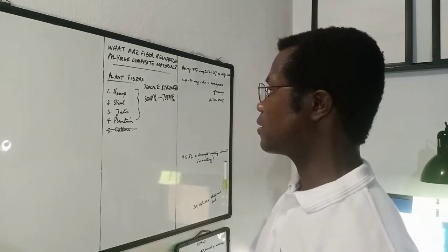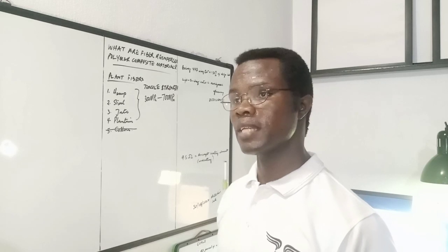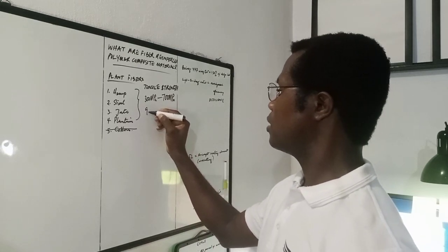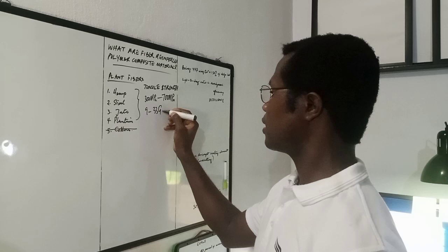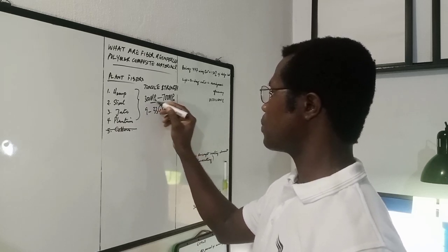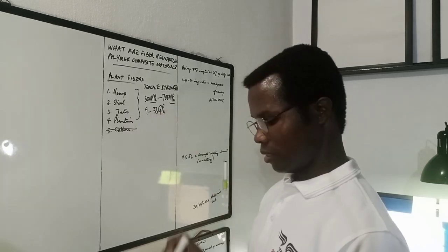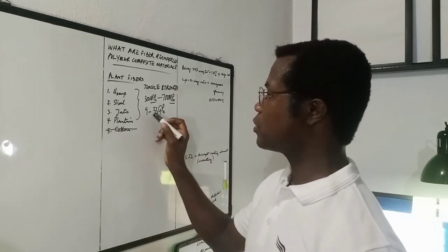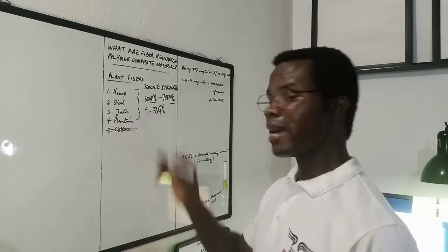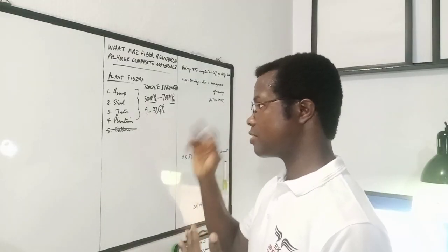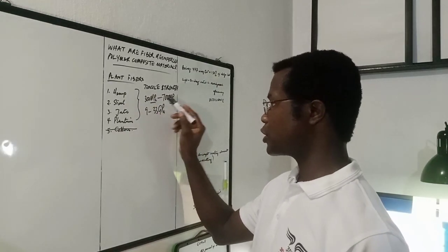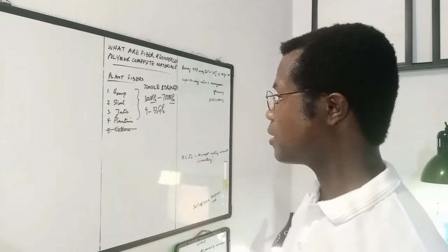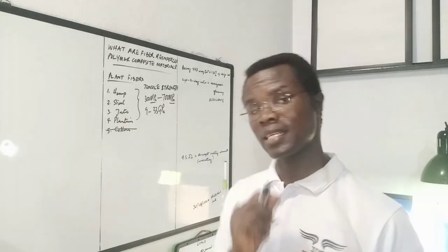And it's a similar case with the modulus of the fibers, the modulus of elasticity or the stiffness of these materials. In general, they fall between 9 to 33 gigapascals. And by the way, these MPa are megapascals for the tensile strength. The unit we're using for the modulus is gigapascals, okay? So in general, they fall between 9 to 33 gigapascals, and that is due to a bunch of reasons that also account for the variation in the tensile strength properties, such as the way it was extracted, what treatments were carried out, etc. But there's a lot of variation with plants, and that's one of the disadvantages also.